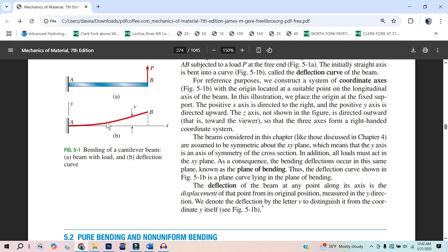This picture, as I said in the last video, this right through here should show you the largest change in the curve, because that's where our largest moment is. It doesn't look like it. It looks like this is straight, like all the curve is in here. I think it's either poorly drawn or our eyes are tricking us. But the biggest change in angle is because of the biggest moment here, and then we peter out to a linear section. This section is very linear right there. So that's why we have a positive moment that goes downward.